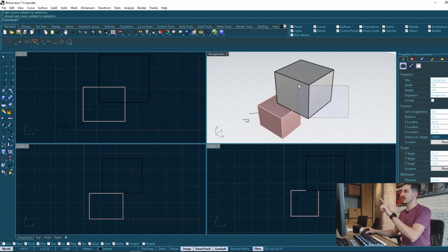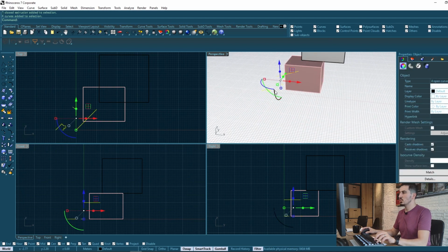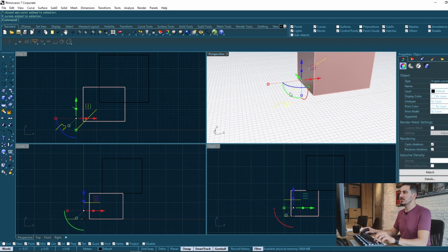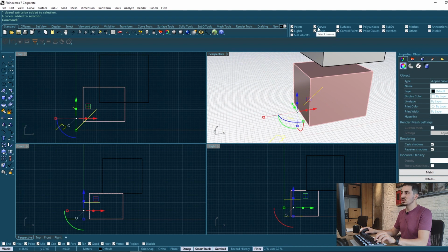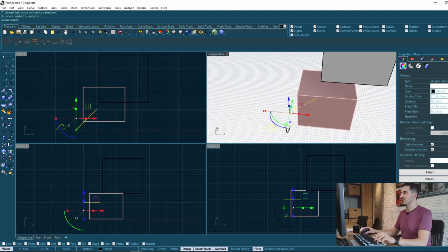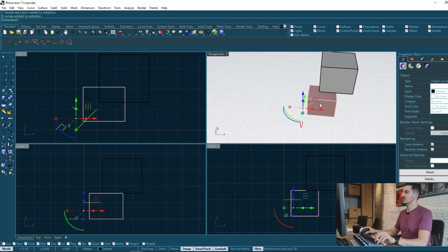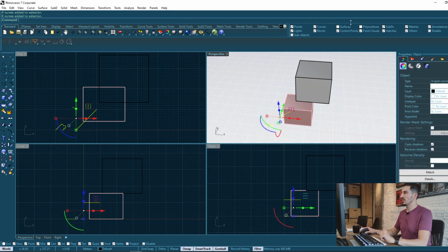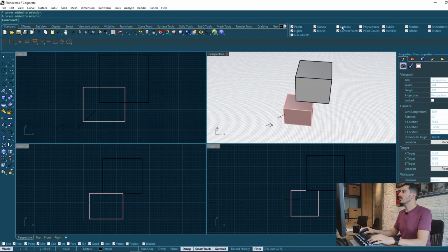And as I can see, it blinks up there, showing me that you can't work with these objects because of this filter. But I can, of course, work with other objects like these curves, which are chosen here. So if I have curves, I can work with them. Surfaces are now turned off, I can't work with them. I will turn these on again.